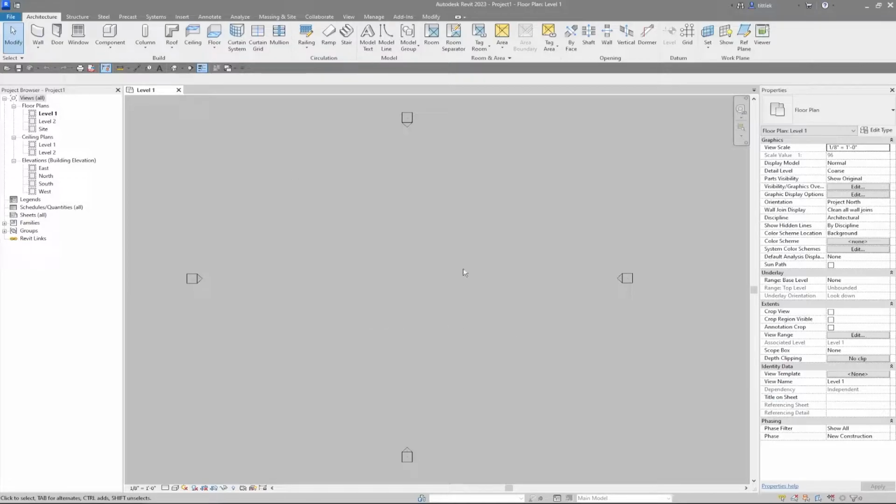So as I mentioned, we are going to start with the walls as we always do when we're drawing a building. I'm not going to review the specifics of my Revit creation method, but I will be using it, so I'm going to be going through those steps as I create these walls. I will also emphasize my method of creating things in Revit, which is typically don't worry too much about being exact when you're placing them in the model.